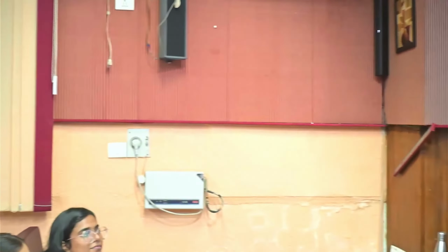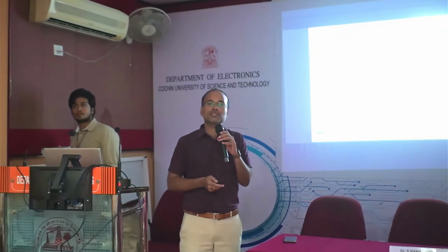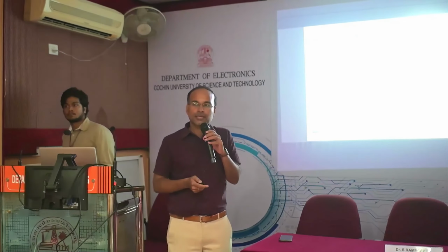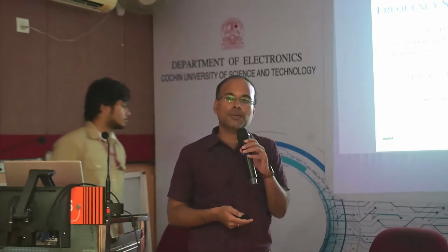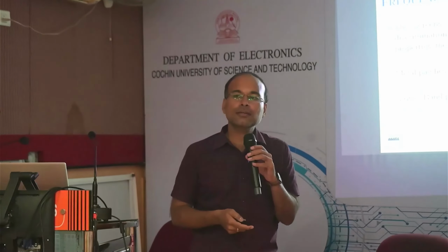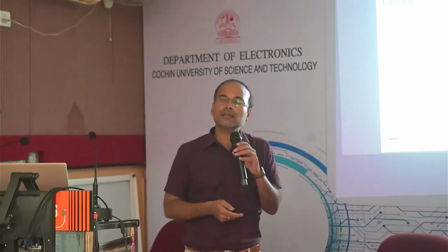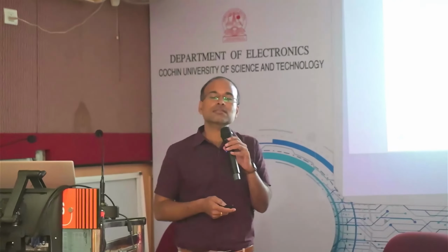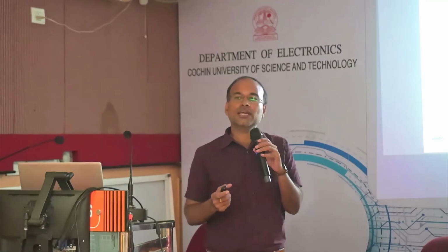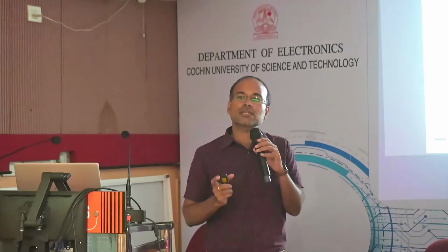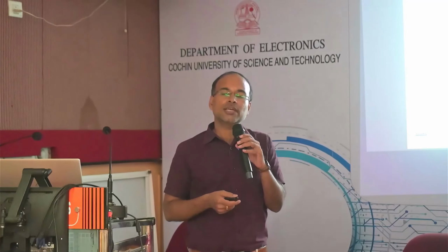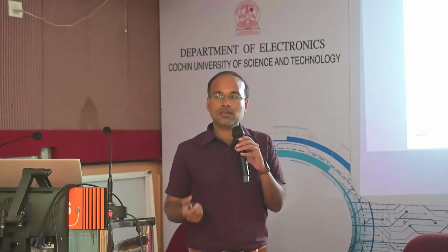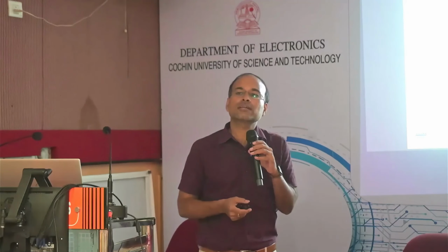Okay, thank you. So FSS is a frequency selective surface. It provides frequency discrimination. It means it either transmits or stops the signal. In the other case, it can absorb it as well. How are we going to do that? By making a two-dimensional periodic array based on the unit cell. Each and every element in that two-dimensional array can be called a unit cell. So that unit cell we have to engineer so that we can make it a band pass or a band stop, or we can absorb the incident electromagnetic signal of our interest.